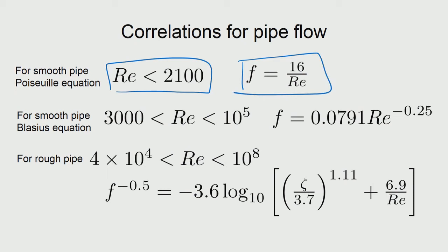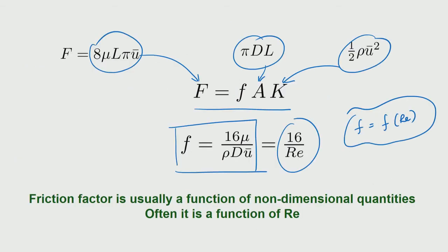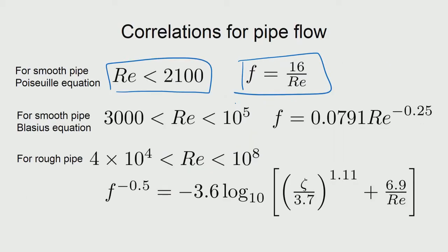Okay, now we can use the same approach, that is, in a given experimental problem, we can measure what pressure drop is causing what kind of velocity, make a correlation and then get f, and make the correlation with Reynolds number as the regression variable, and then see how the friction factor should evaluate. And that is given in many open literatures that are available, and there are results for a very wide range of Reynolds numbers, and therefore they are also very popular.